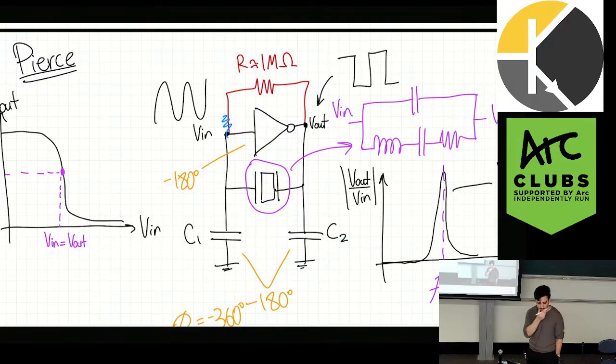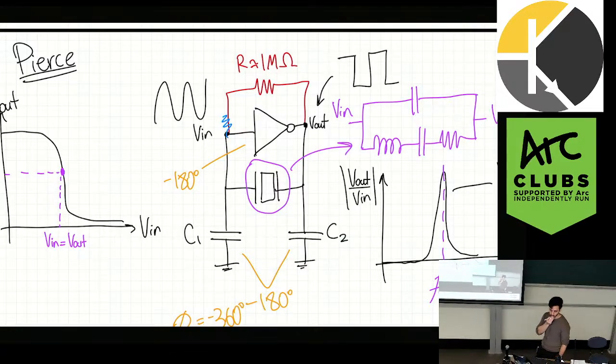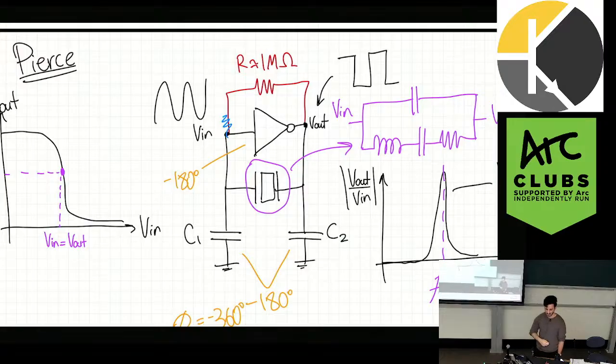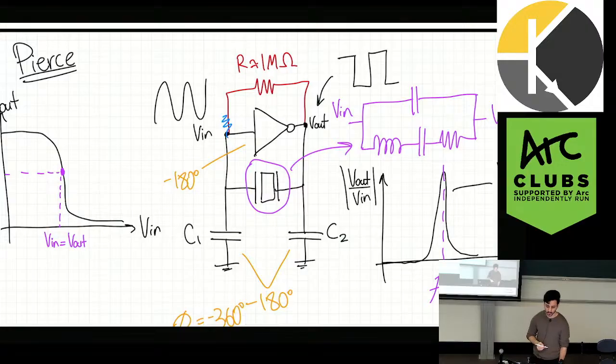So you're right, it might, but I wouldn't say it's too significant of a problem. Generally we tune it such that that isn't a problem. So this does require tuning. There would be some output impedance of this inverter, because the inverter has to be pulled high or pulled low, and to get to high or low, it has to go through essentially a transistor which has resistance. So it would be there, but it wouldn't be enough to affect it, I'd say. Generally they're quite small.